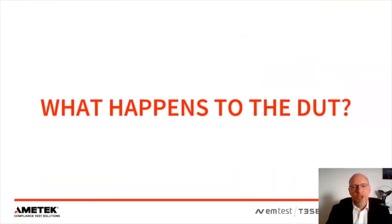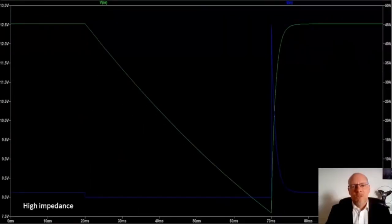So let's take a moment to look at what happens to the DUT during the testing, either what happens in the car in a low impedance or a high impedance event. Specifically in this case, I prepared a couple of simulations to show what happens to the DUT, current and voltage curves, during different types of events. So the first simulation I prepared is a high impedance simulation, and this simulates like bouncing relay contact, loose contact in a vehicle, something like that.